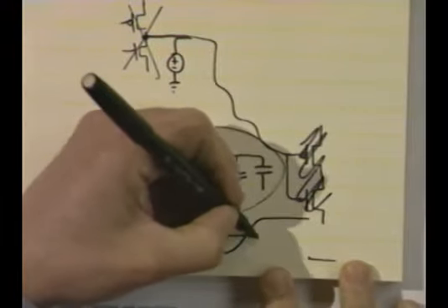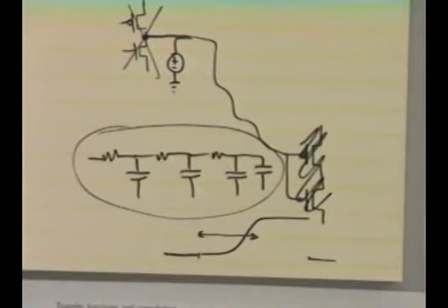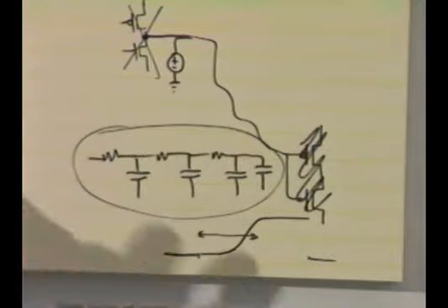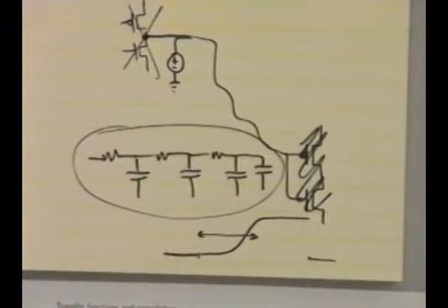That's the delay. That's a critical one. And just to see, I don't know if you get the idea here, if I made the wires really thick, so the resistances were really small, what do you think the delay would be? Small or big? Small, right? Big wires, RC is a rough time constant.